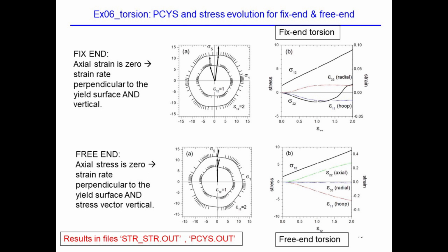Now, this is for 100% deformation. As you continue the deformation, as you can see, the yield surface tends to rotate, and now the normal changes. So the forces go from compressive to tensile. If you hold the ends, it starts going from compressive to tensile, and then you can see here, if you plot sigma 2, sigma 2 starts at 0, goes through a minimum, and then keeps climbing and becomes positive. Sigma 1, 2 goes practically linear all the way.